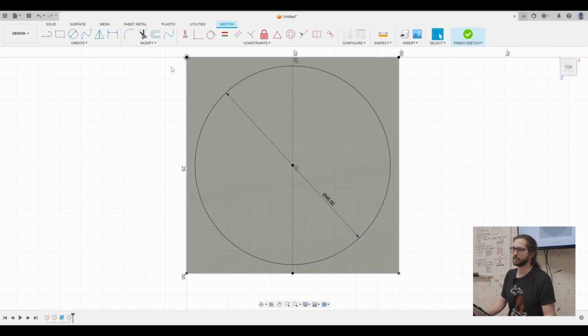And you'll notice that the circle is now also black on the drawing because the line was already constrained, and the midpoint of that line is necessarily constrained. So a circle defined off of that constraint is also already constrained. So that circle exists only in one place.